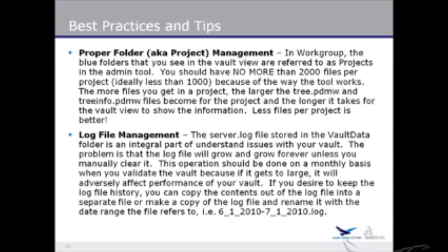generate the vault view. So the smaller those tree.pdm files are, the faster it's going to generate your vault view for you. And this is going to improve performance a little bit inside of SOLIDWORKS. So the more sub-projects you have, the better. The fewer files per project, the better. It's going to help out.